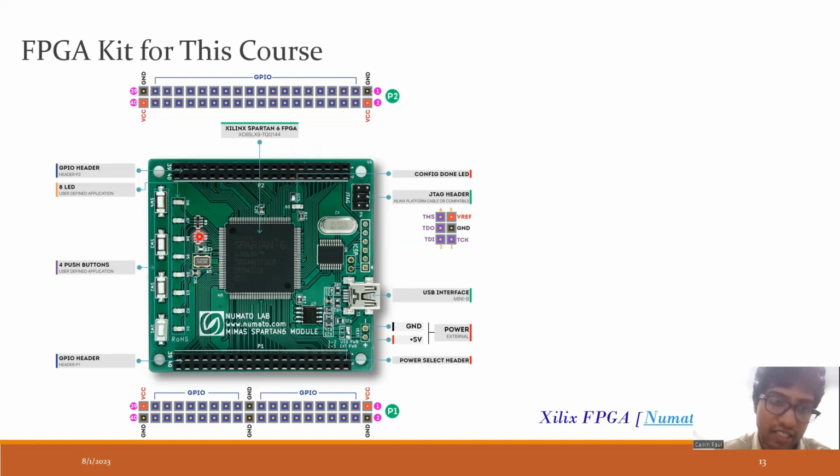Then these LEDs are there. We can program that if a fault has occurred, the LED must be high, it must be on. If one fault has occurred, this LED should be on. If over voltage has occurred, then this LED should be on. So that way I will know what fault has occurred. Then there are certain switches. If I press this switch, then the mode of operation should change from this mode to another mode. All that I can program.